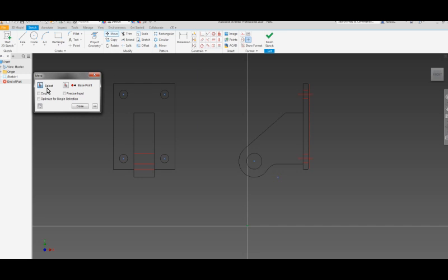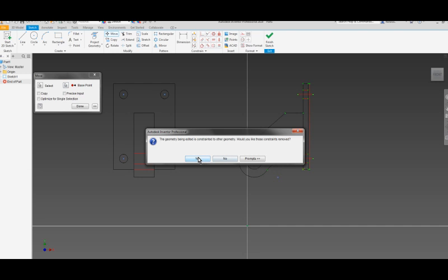Okay, selection: click and drag either a green or a yellow window to select everything. Everything is selected, and we can see that it's green. Then I'm going to use my base point and indicate where I want to move it from. Well, I want to take that corner and move it.